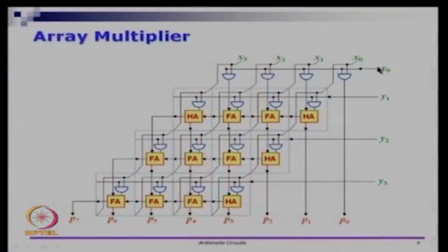So, what we have is, if you do the circuit here, it is taking partial products which are coming from two levels, adding them together, and generating the sum, and that sum can be added with the next partial product array, that will give you the next sum and so on. You do that for 4 steps, y0, y1, y2, y3. At the end of it, what you will get is the final product. I hope that this is clear to you.